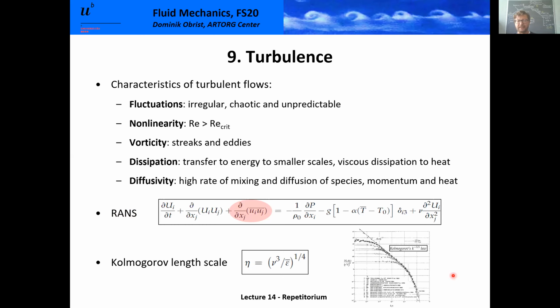We also looked a bit at the theory of homogeneous isotropic turbulence, like the prototypical turbulence. We saw that we can come up with the smallest scale that is present in turbulent flow, the Kolmogorov length scales. It's the whole Kolmogorov theory. We had some results on that. Maybe you remember this example we made with the blender, where you create turbulent flow with an electrically driven blender, and we could compute how small the smallest vortical structures are in that object.